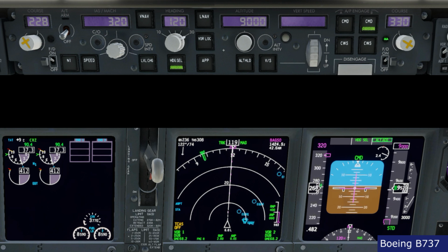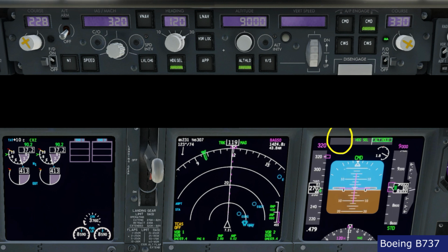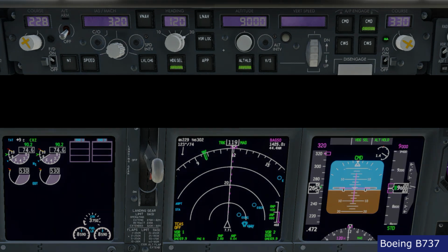And now, you see, I am in auto acquire. As soon as I go in auto acquire, now the thrust became responsibility of the auto throttle. But because the auto throttle is disengaged, now the thrust is my responsibility. I have to personally think about adding thrust. If I don't do that, the auto throttle channel tells me that there is nothing on the auto throttle. So if I don't add thrust, obviously we'll end up in a stall.